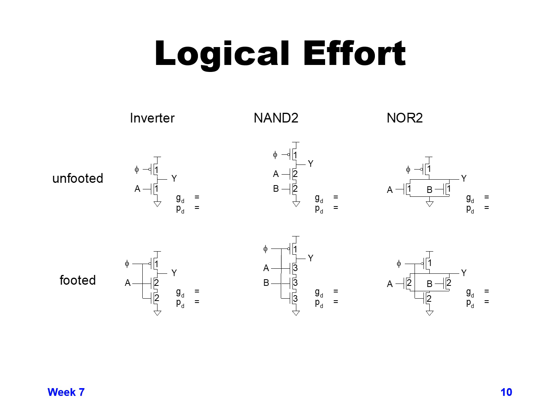Okay, so hopefully you've done that, or if you haven't, I would recommend at the end of this slide going through and comparing versus static CMOS. But if we look at the unfooted inverter, the logical effort, we have Cin only going to a single NMOS of size 1, so that's 1 over our normalized 3 for our logical effort, and then the output is connected to 2 size 1 devices, so we have 2 over 3 for our parasitic effort or parasitic delay.